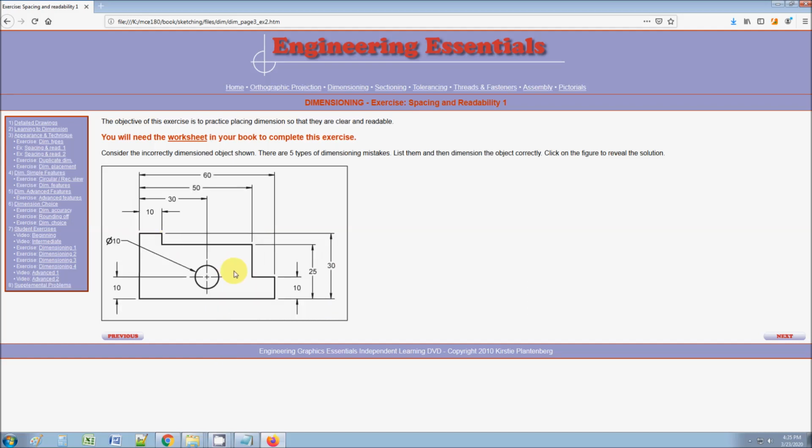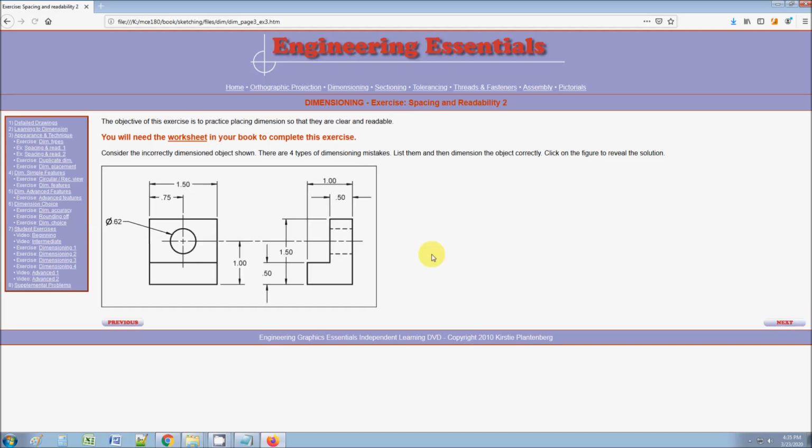So here's the solution to that example. Okay, let's take a look at this one. Alright, so as you can see, this is not aiming towards the center. You see how it's missing that? Okay, gotta be careful. Also, you see how it's underlined? That's not good. The ANSI standard says it's got to look like that. When it's underlined, that means we're using the ISO standard. That's okay for the ISO standard, but for the ANSI standard, it's not okay.